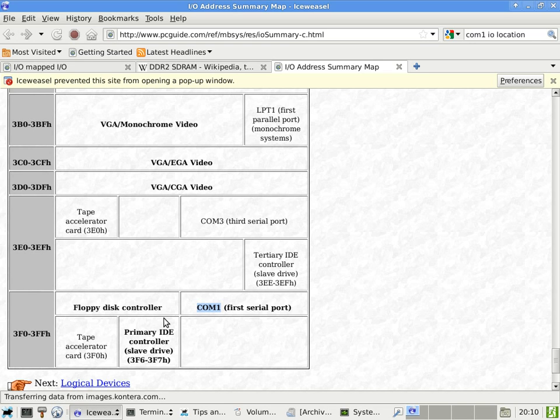Look at this one here, okay? 3F0 to 3FF. It seems like an address, okay? But it does not correspond to memory address 3F0 to 3FF. In other words, if you look at memory for your PC as one big, huge binder that has 4 billion pages, this is another binder. Your PC has 2 binders.